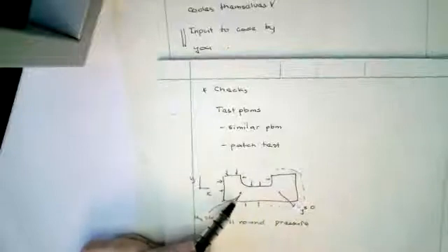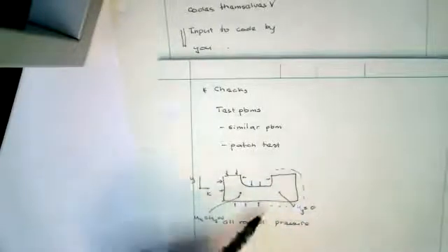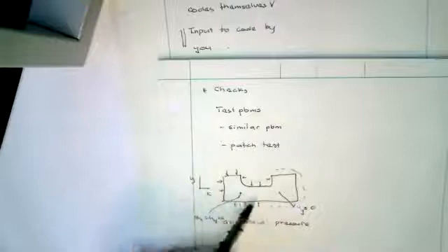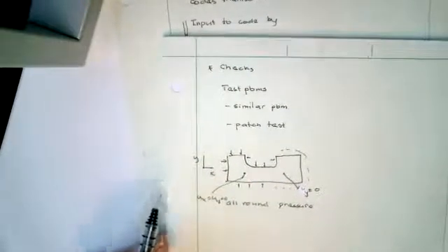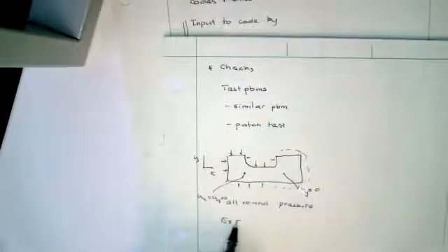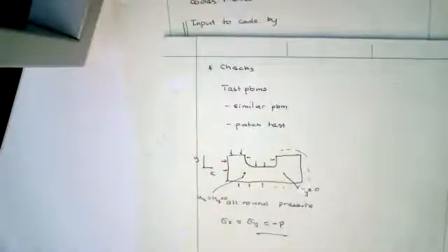So if at one point I tell it ux and uy equal 0, that stops it moving this way and this way. It could rotate, so I come out here and tell it not to move in that direction. That'll stop it rotating. You put it under all-around pressure, then the exact answer is constant stress. And this works for any problem you're doing.